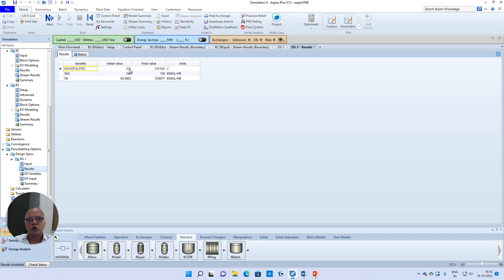So when we started with 200, 100 was the inlet flow rate, the outlet flow rate is 90, so the conversion is about 9.4. But when we increase it to about 360 degrees centigrade, now you can see the 100 moles per hour of propane is the entry feed rate. At the exit, we almost had 19.9. So what is the conversion? 100 minus 19.9 by 100. So we are able to get to 80% conversion. So in this way, you should be in a position to calculate most of the calculations involved with equilibrium reactions.